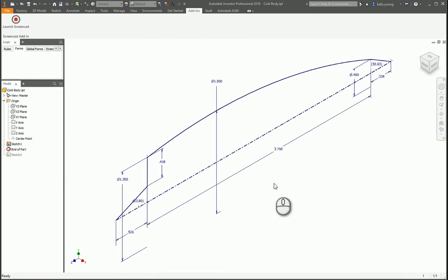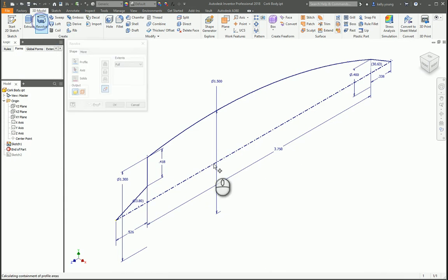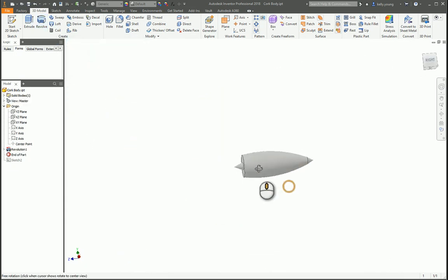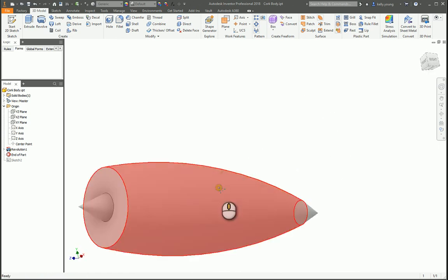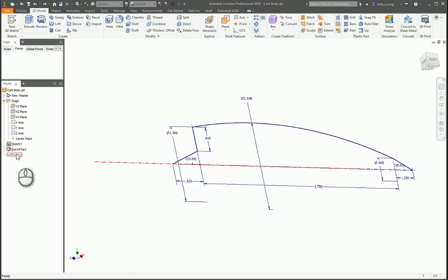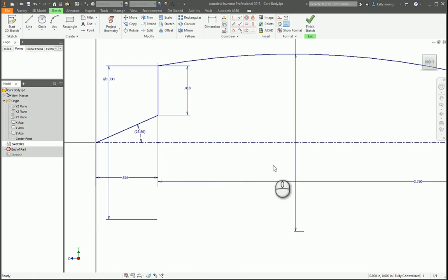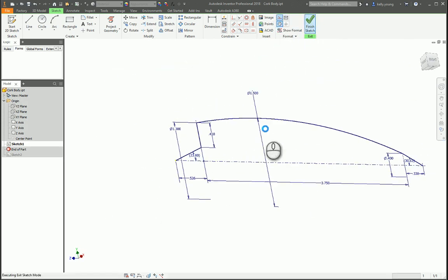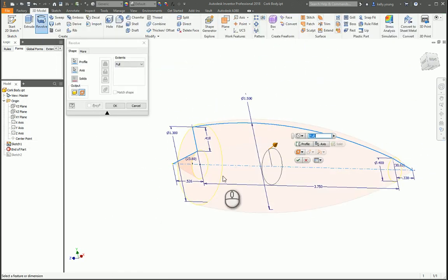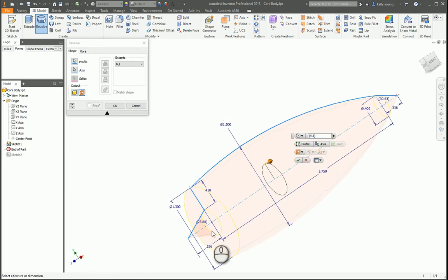Finished our sketch. Now you were talking about mirroring to a second sketch. I think you're talking about revolving. So I think that's what you're looking for. Just revolving for a cork stopper, probably for a wine bottle or something. So instead of having the second thing, you can revolve around that sketch if you wanted to. I can't remember if this works or not. Can you revolve around that one? No, because then it just gives you a surface. So if you don't close up the line, which is probably what you were doing beforehand, it doesn't revolve around it.